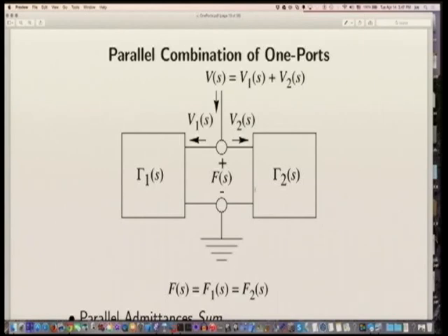But the more complex case is called the distributed case, and it does happen in circuits, but they're like microwave circuits. So in microwave engineering, they're dealing with traveling waves in circuit wires. And so things aren't necessarily in phase. And you have to be really careful. How do you distribute a clock in that situation? How do you know that all of your elements are getting the rising edge of the clock at the same time? Well, you have to be really careful. If transmission line effects matter, you don't have that guarantee.